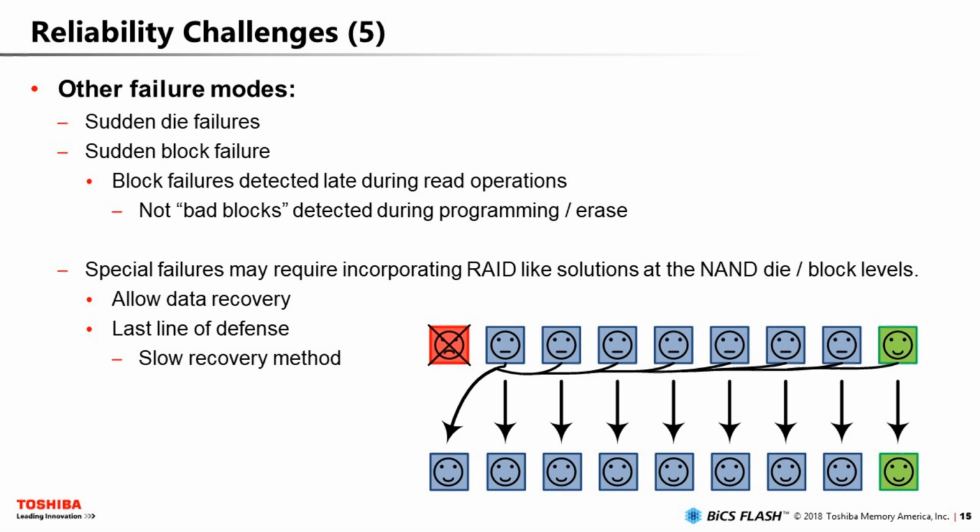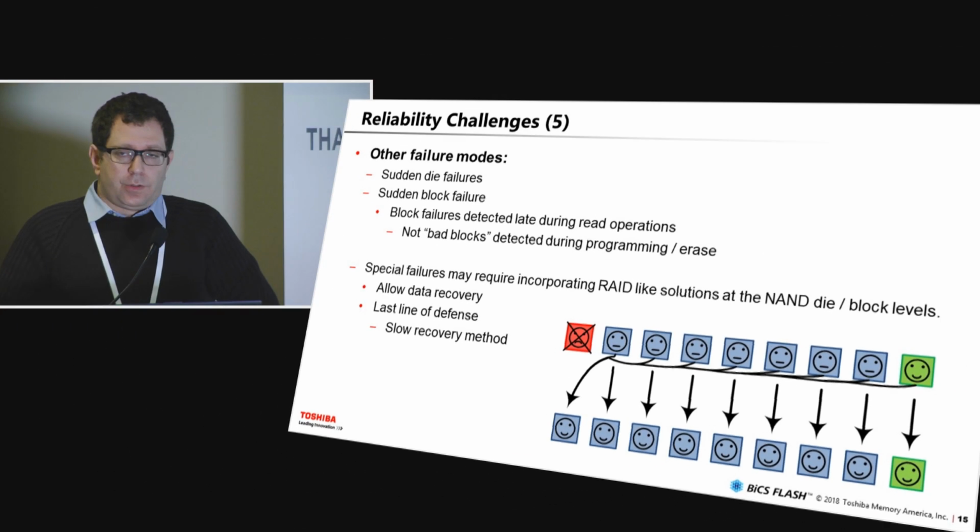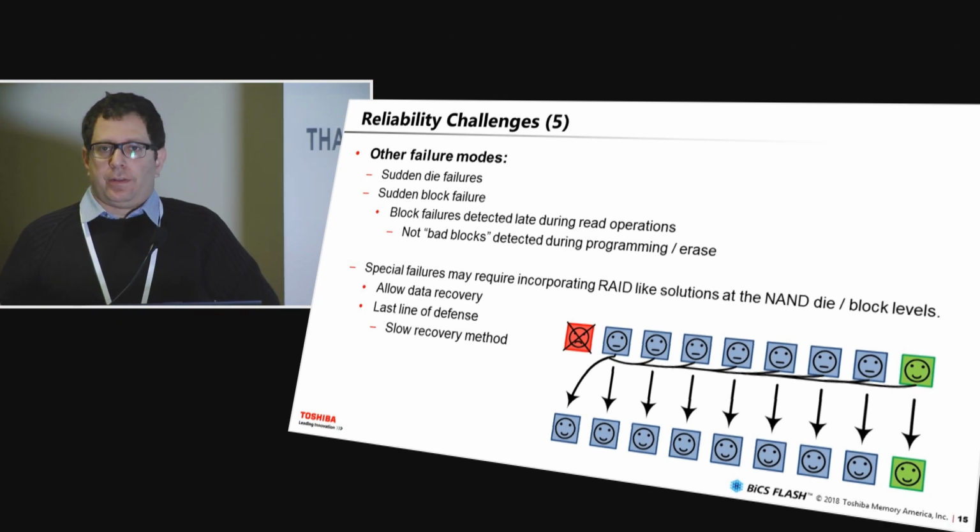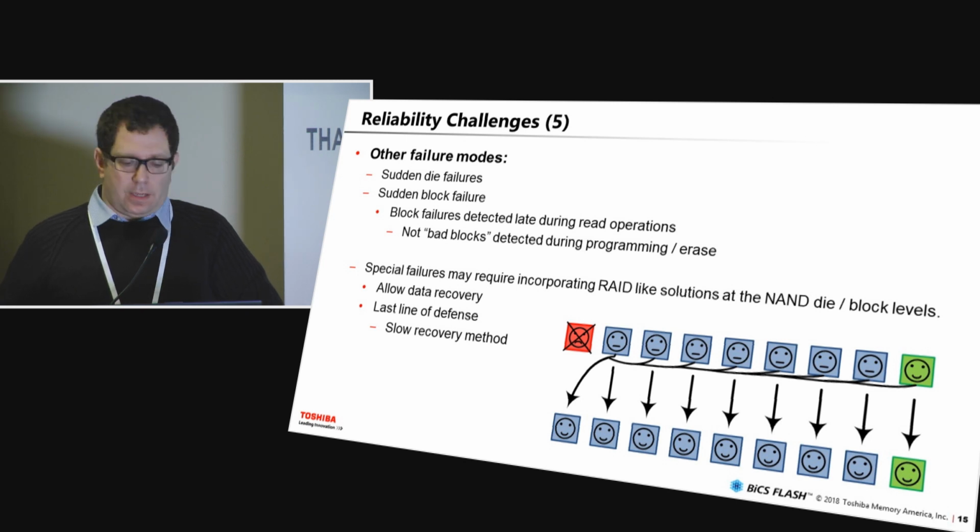For this reason, some of the systems also have RAID, or some type of RAID, where you basically store additional data. Per several blocks, you'll have a RAID block where you'll store some RAID function of the other blocks, such as to allow you, when you have a catastrophic failure on one of the blocks, to recover the data and copy the recovered failed blocks and all others to new locations. So these are many of the challenges that you have, and there are many more challenges in the NAND controller.